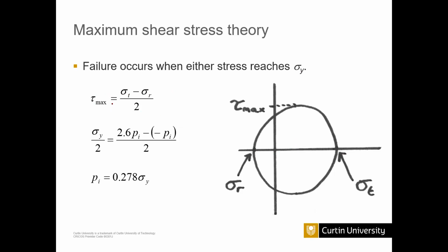So you can now get the relationship between the tau max and the yield strength. Normally, the nominal stress and shear stress relationship, I already explained these things. So tau equals 0.5 nominal stress.